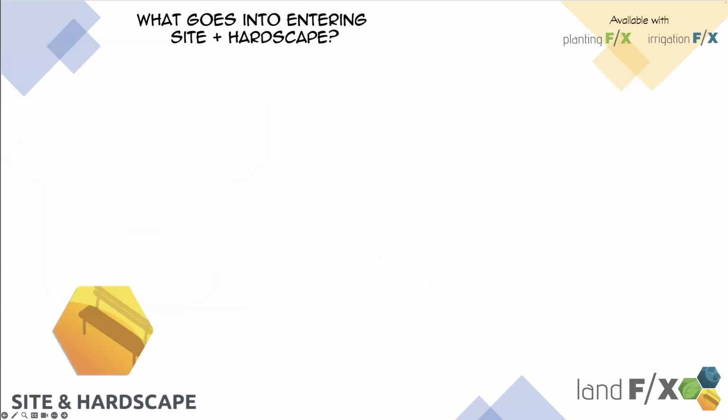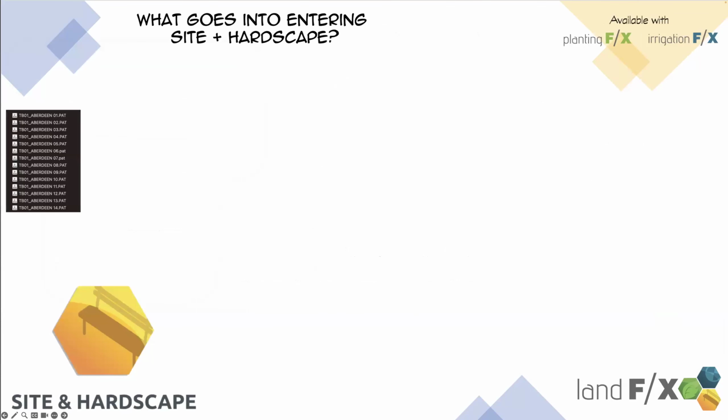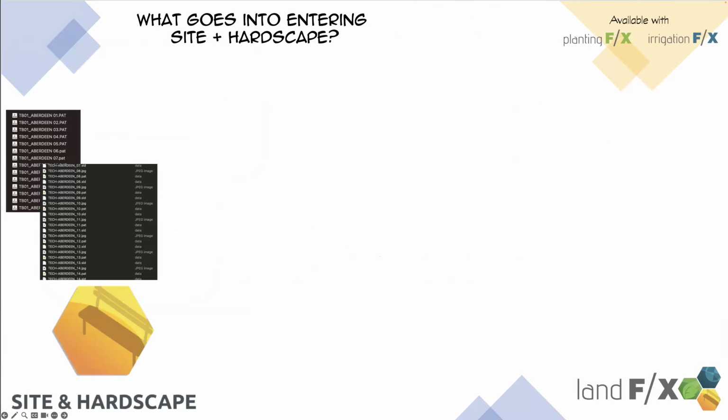Finally, when we go into site and Hardscape, a lot is received here. So we receive files from the manufacturer that are titled directly from what makes sense in the manufacturer's organizational data entry. We can conform that to CAD standards and try to be as consistent across the board, which is why we have super strict guidelines. We change each file name to a uniform name. On a granular level, we also go into each and every inner pat file to ensure that the file name in the pat file matches the actual file name to avoid any errors being thrown or rendering that file unusable.